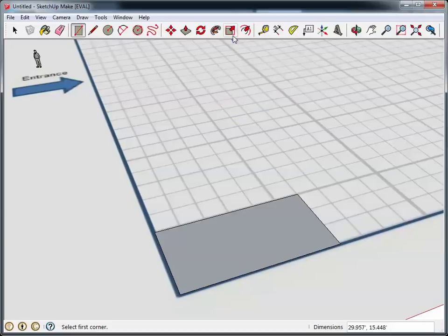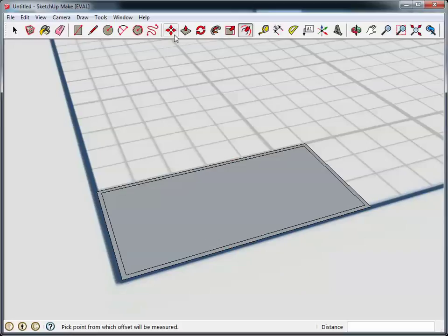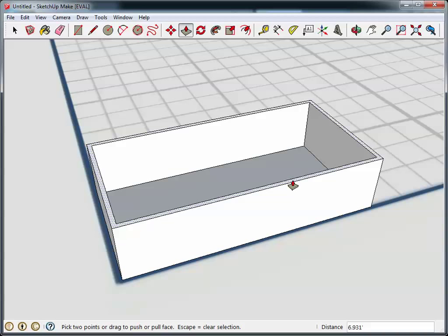And then I could use the offset tool right here. Click here, and let's give that a little bit of wall thickness. And you notice it's having some trouble selecting that. What I've again found, if you come over here, click that surface, use this, then pull it in like so, 0.5 feet, like that. Zoom in. I can click the area that I'm trying to extrude outward or upward. Pull this up 12 feet. Use that in every case.